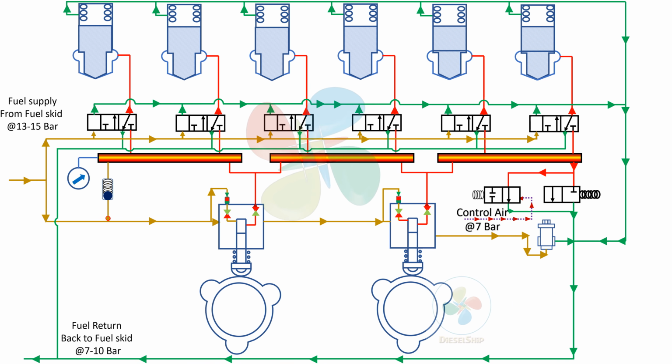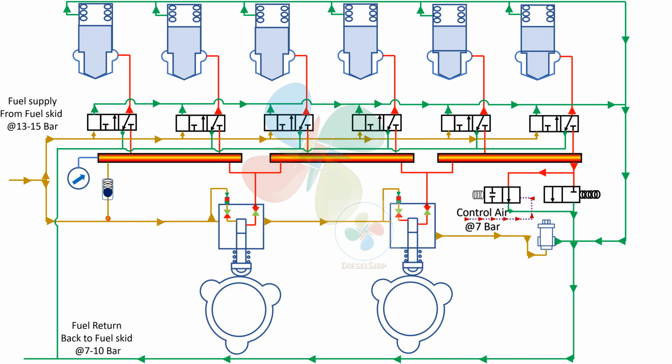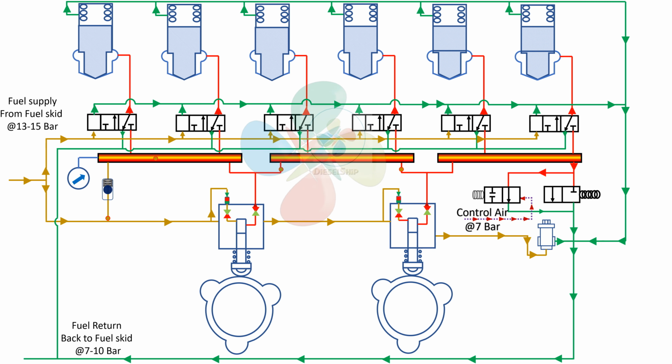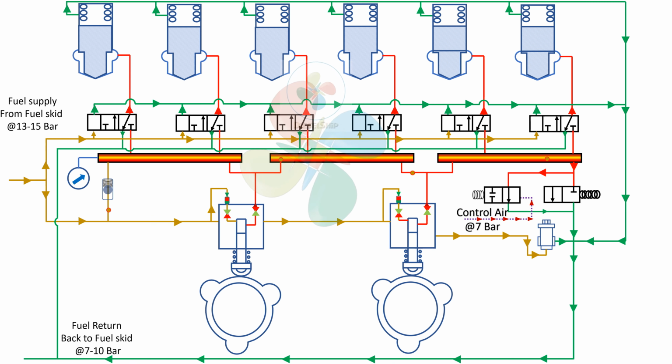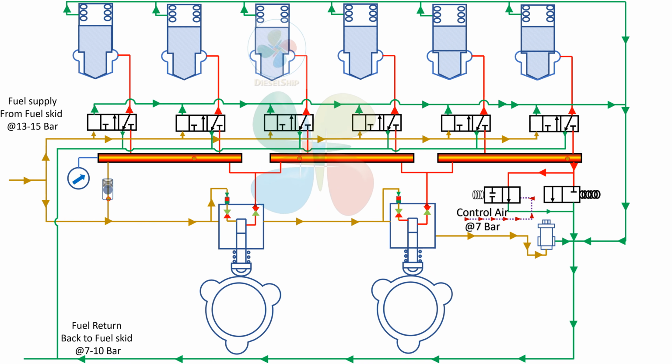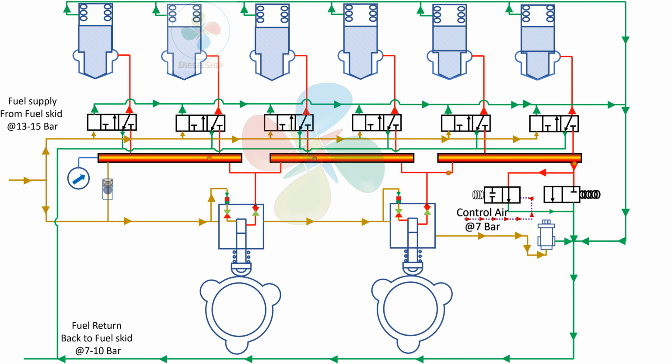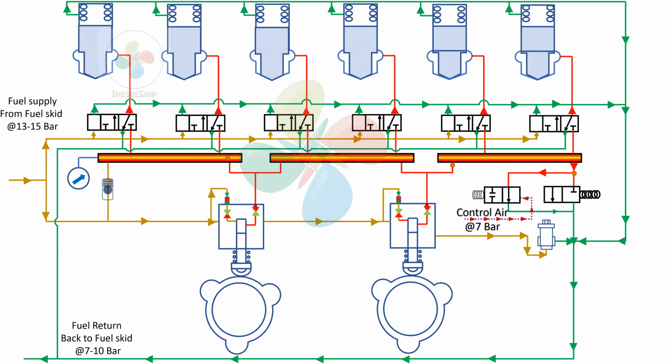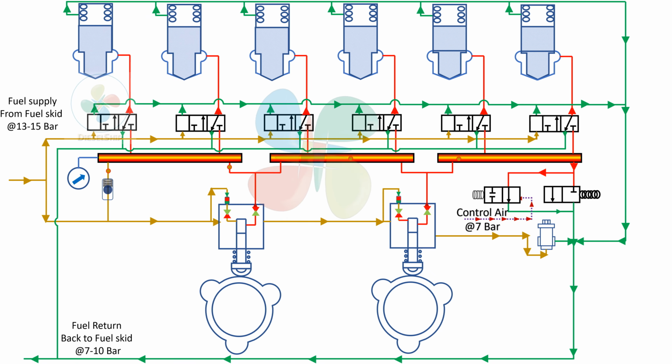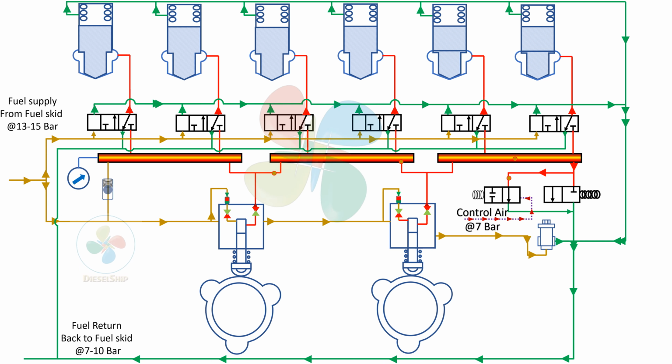Now let me simulate opening of the non-return valve for C. The ball has moved and the fuel is going through the accumulators as well. So the complete fuel injection components are now circulated by the fuel, right? The fuel returns back to the buffer tank as we already discussed. Right, we'll see the rest in the next chapter. That is going to be the main injection animation. We'll see you in the next chapter.